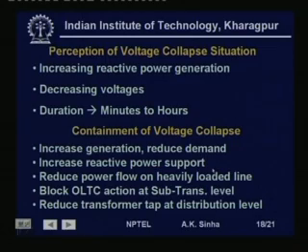In fact, sometimes it is advisable to reduce the voltage at the load ends, so that it reduces the load demand, that is both the real and reactive power load demand, and thereby the loading on the transmission line is reduced to some extent. This kind of action is many times called a brownout situation, that is, reduction in voltage is going to reduce the load, and that restores the voltage drop on the line to a lower value, because now the line loading has reduced.